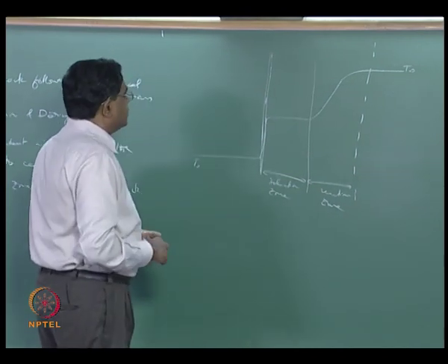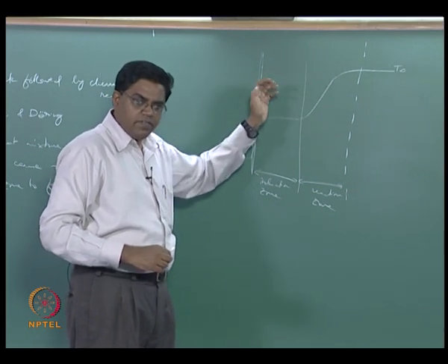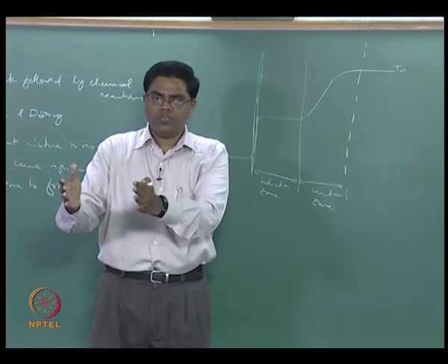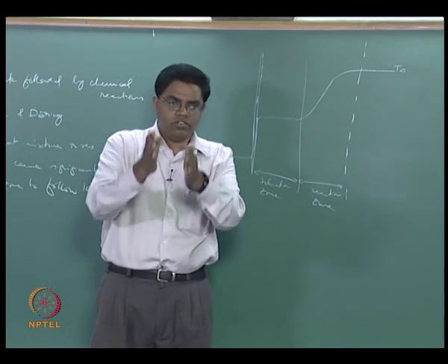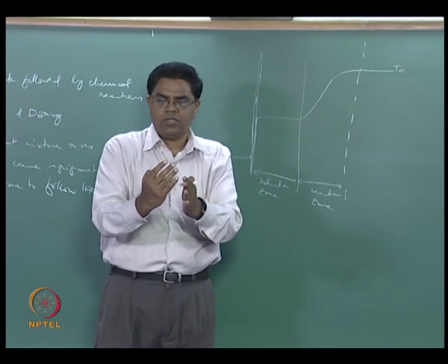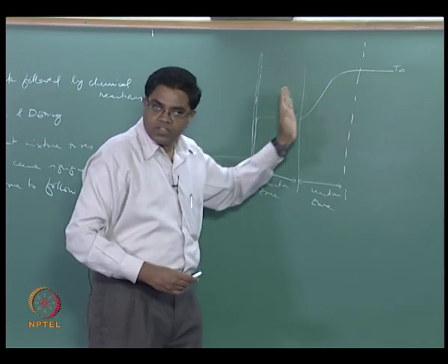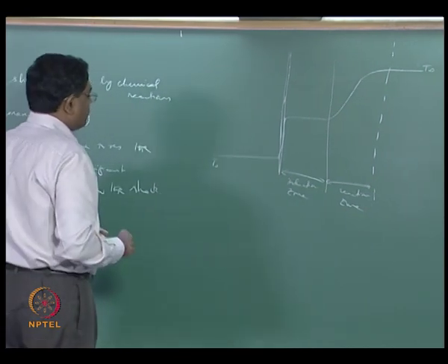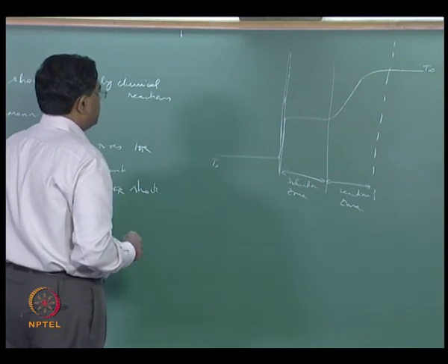this sudden rise. This rise, unlike in deflagrations, has a significant convective effect. In the case of deflagrations we had a preheat zone which primarily contained a conductive-diffusive balance with no reactive component, and then the reaction zone where you had a reactive-diffusive balance with hardly a convective effect. But here you have significant convection happening in this reaction zone as well, because you have very fast flow rates there.